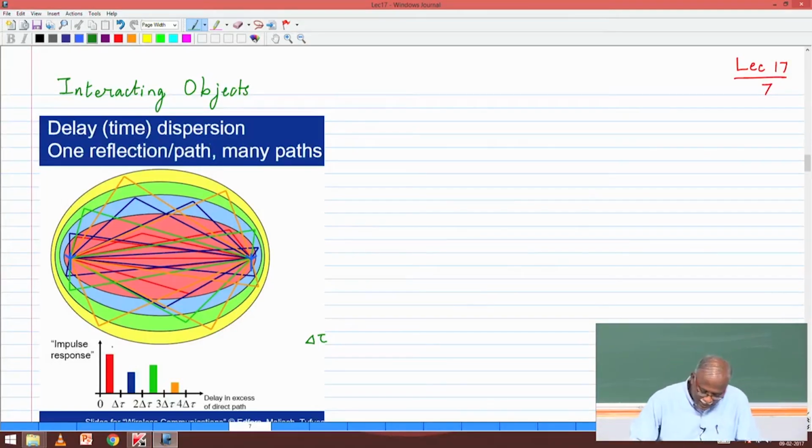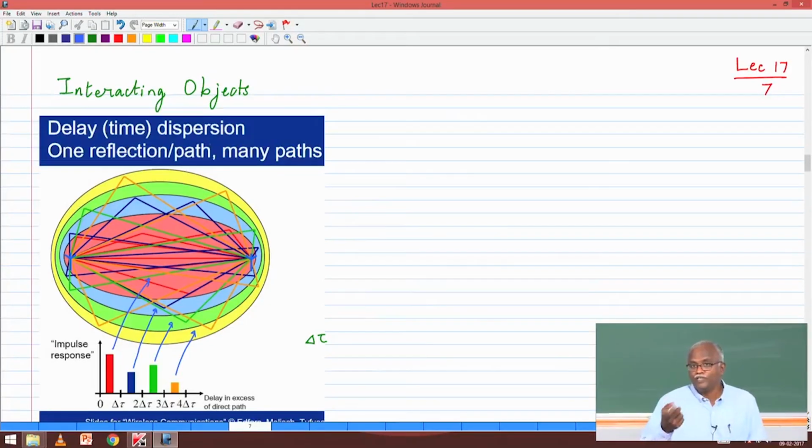So basically this red corresponds to the portion from the innermost circle. The second one comes from the blue, the third one from the green and the yellow. Is that clear? Depending upon the bandwidth of the signal I am working with, the number of paths that show up changes. Now if I have GSM with a time resolution of about 500 nanoseconds, and the entire multipath spread is only 200 nanoseconds, it doesn't matter how many multipaths there were, it will look like a single multipath to me, because I cannot resolve between them. A very, very important concept.